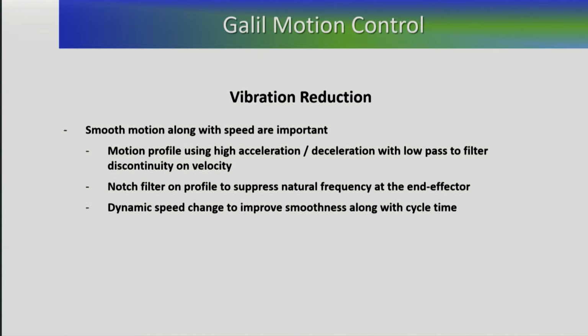In instances when you have dual loop position sensors, where you put the position feedback on the load as well as on the motor, you can look at the position of your load and know that you have vibrations. You can characterize the frequency of that. When you don't have the sensor or position feedback on the end effector, how do you characterize the frequency?